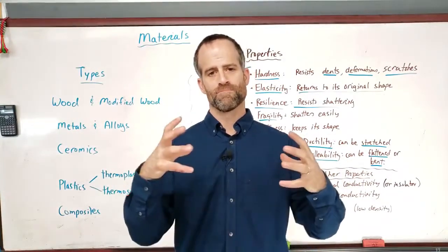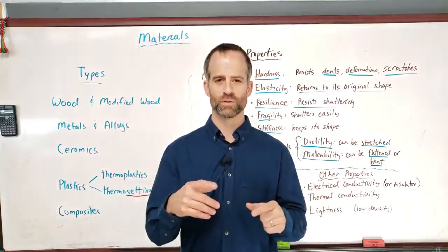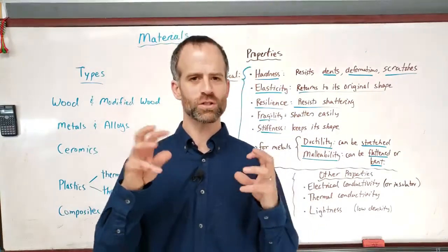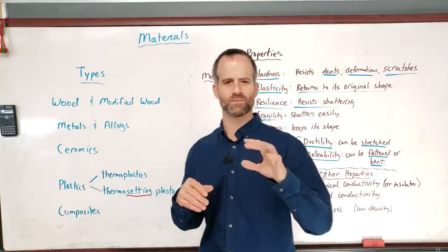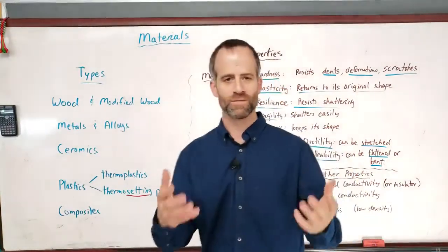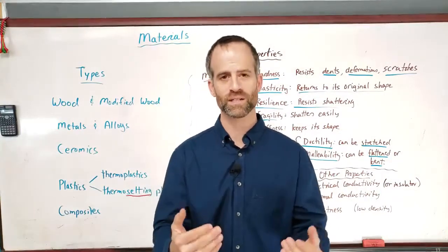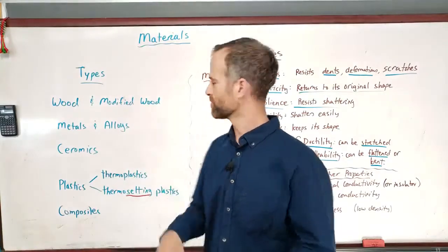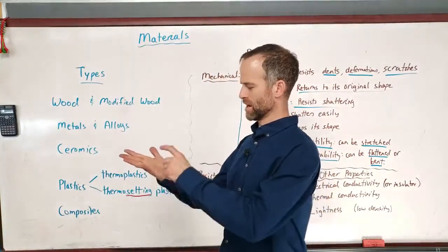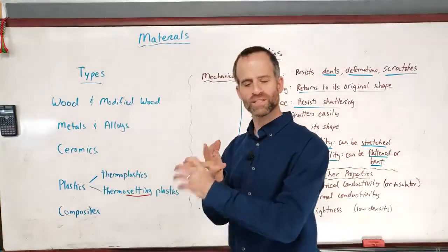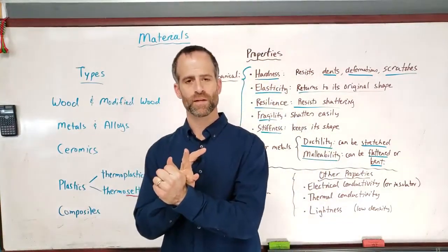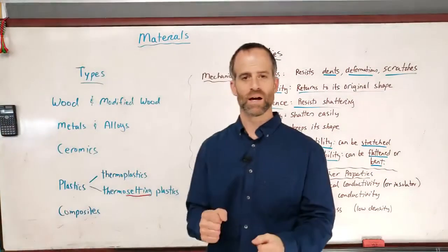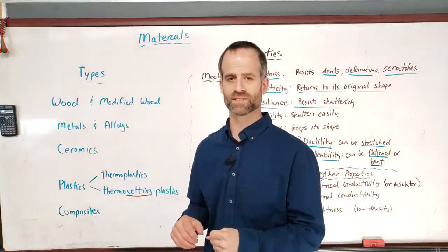Okay. Typically those solutions, they're a copper solution, so if you look at treated wood, technically it's called pressure treated wood. Usually it has a slightly greenish look to it. They've come up with another process, which is now it doesn't have that color. But if you were making fence posts, you would buy wood that is treated with a chemical so that the wood, even though it's in the wet dirt all year long, it doesn't rot. So we modify the property. How? By coating it with something, paint or varnish, or by soaking it with a copper solution or something like that, right? You can also heat the wood up, and that makes it more resistant too.